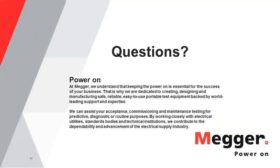Well, the reason for that is because by that time, you're measuring so little current that you're not going to see very much of a change from 1 minute to 10 minutes, and you're getting a low PI, and people are conditioned to looking at the traditionally accepted PI values and getting the wrong conclusions.